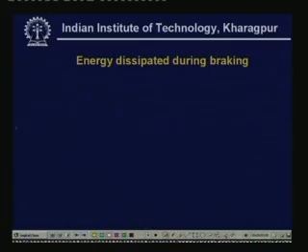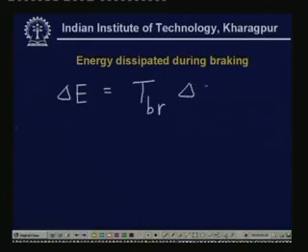So, here the total change is given, and that is equal to the braking torque, let us say TBR, times the total angle delta theta, and this is the total energy.